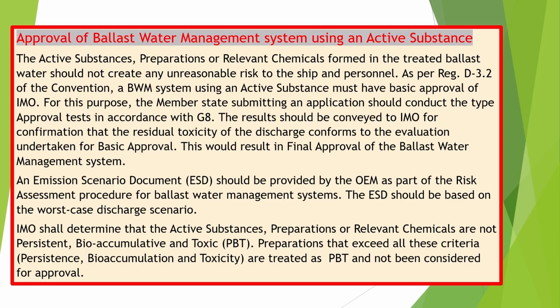IMO shall determine that the active substances, preparations, or relevant chemicals are not persistent, bioaccumulative, and toxic, PBT. Preparations that meet all these criteria, persistence, bioaccumulation, and toxicity, are treated as PBT and are not considered for approval. The approval process is indicated in the flow diagram.